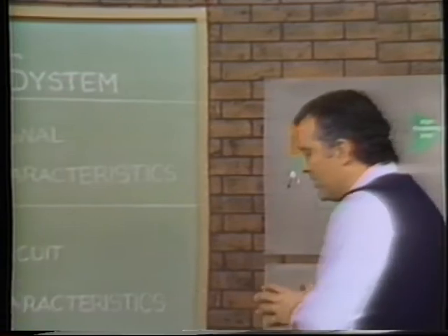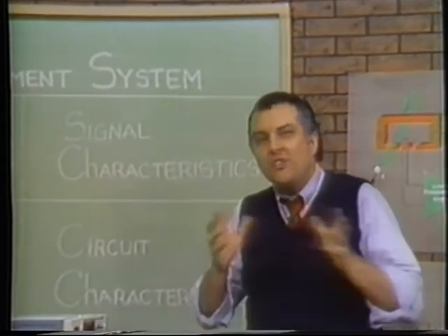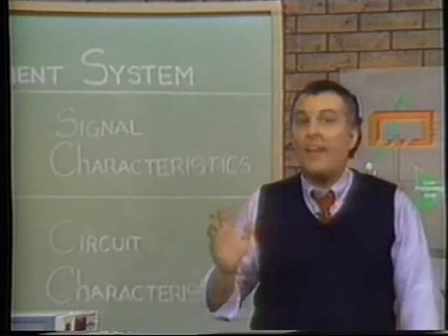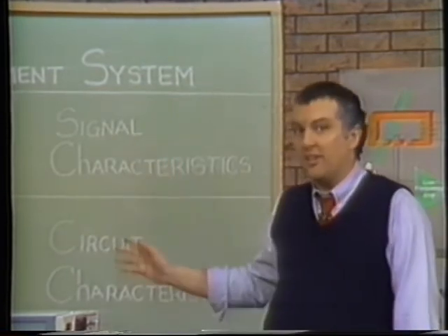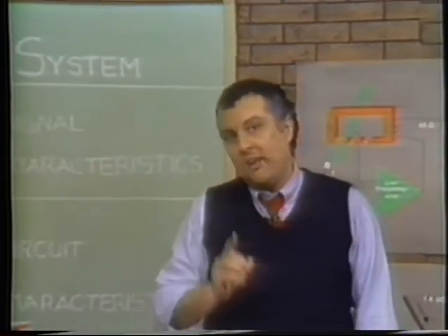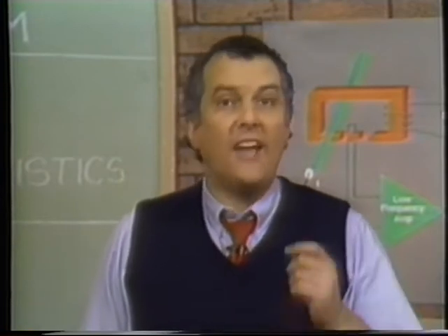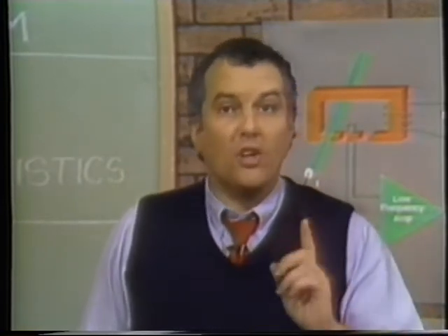Passive probes, active probes. If both are correctly suited to your oscilloscope, when do you choose one instead of the other? That depends on your signal and circuit under test. Remember, at higher frequencies, active probes do a better job of isolating the circuit under test from the scope. This isolation reduces circuit loading and allows the truest representation of the signal. The high input resistance and low input capacitance of the FET prevent DC loading, high frequency loading, and signal amplitude loss. And the low capacitance gives you the best rise time possible.